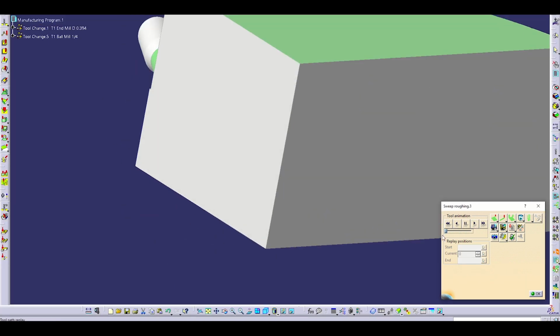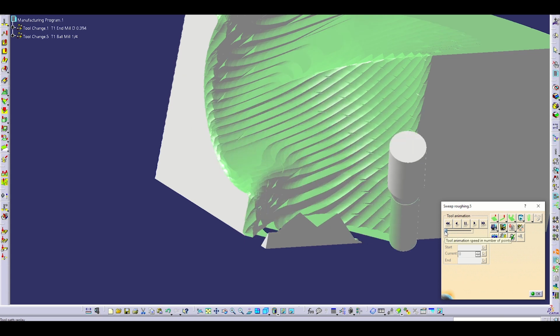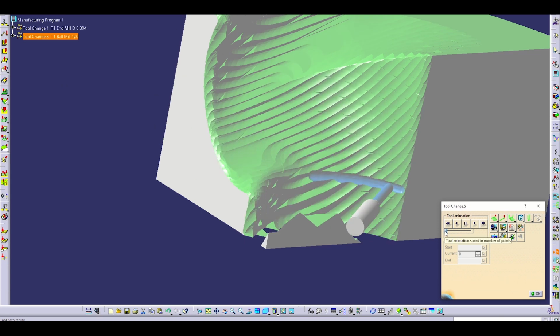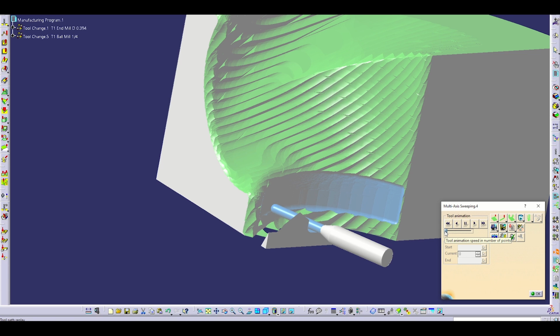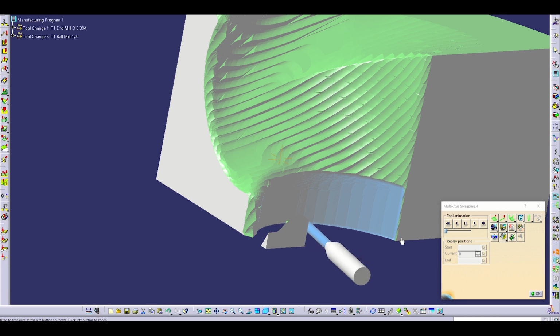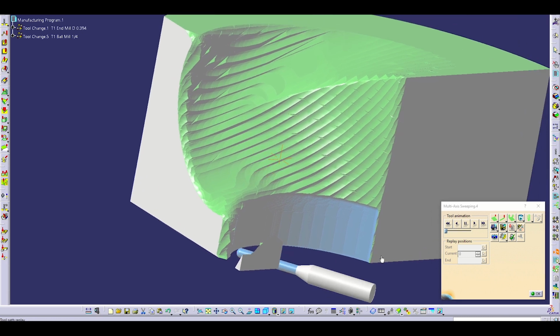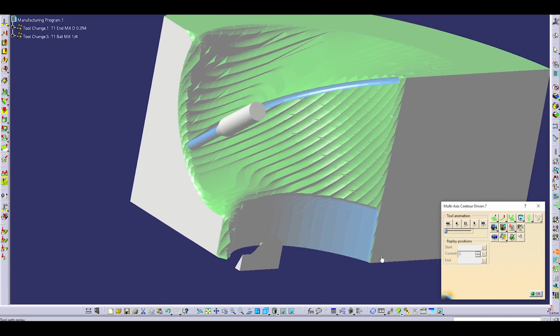But yeah, so the main things to take from Chapter 6 and the 5-axis is really when you're doing these multi-axis functions, you might have to manipulate the tool axis or the view axis and the lead and tilt if your part keeps going in or your tool keeps going in and going through the part. Obviously that's not good. In 5-axis, most of the time that's going to be because your tool axis is wrong. So go in and mess with that a little bit, rotate it around.